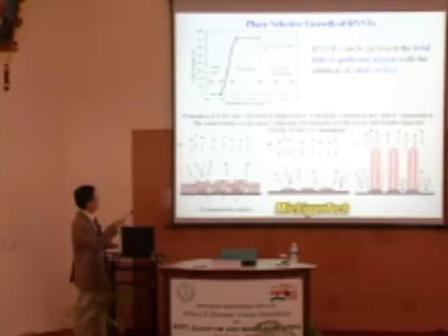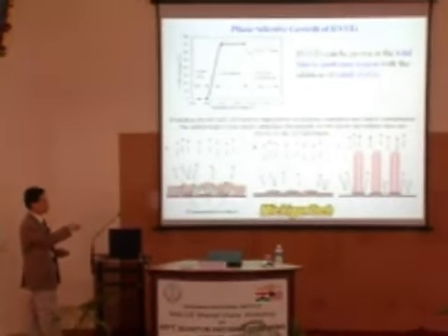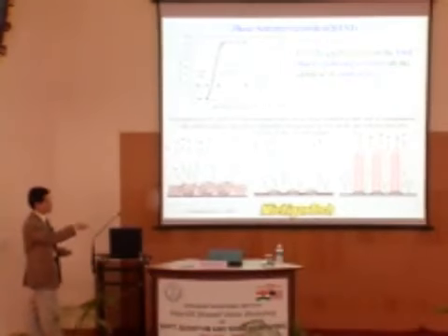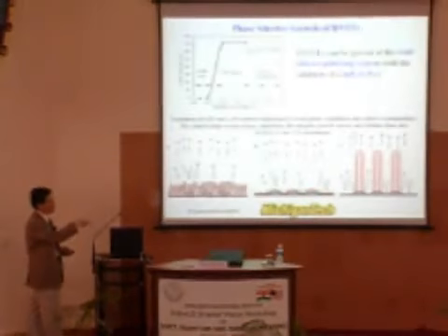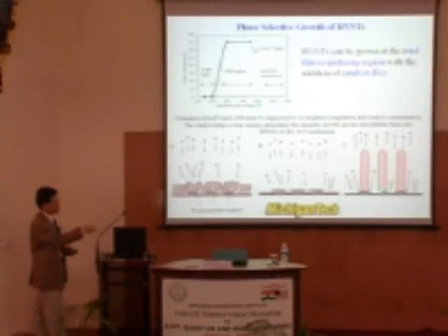As I told you, if you apply low bias voltage, you will create boron nitride films. If you apply a high enough bias voltage, you have very thin films. If this is too high, most of the atoms will just bounce back, except those absorbed inside the catalyst here, which will allow the growth of the tubes.